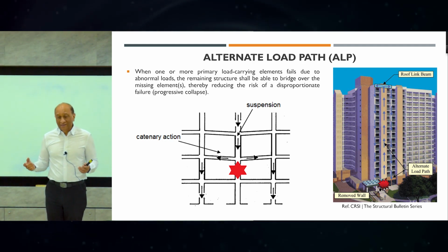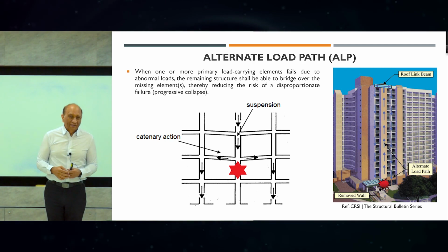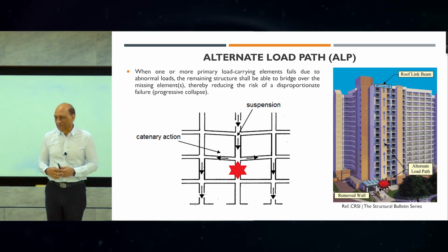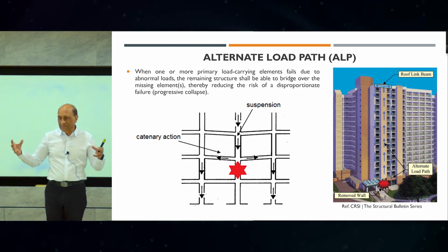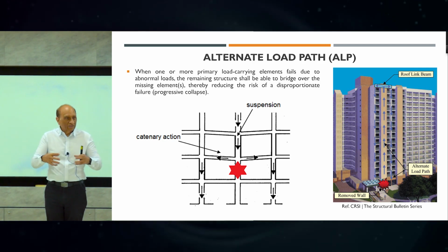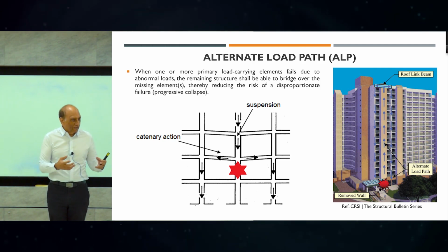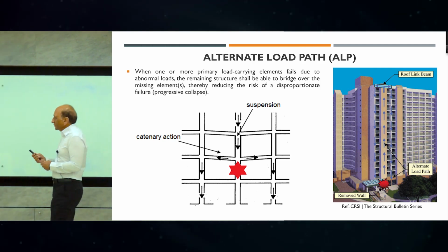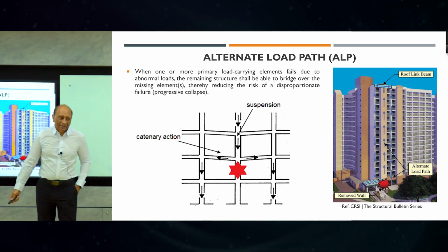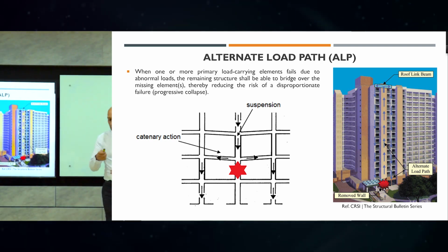And you find, surprisingly, that a lot of columns can be taken out and the building won't fall, because there is a redistribution mechanism in the building. Because of the stiffness, it carries the load back to distribute to other places. It will have a deflection, but not failure. Okay, so that is something that, in fact, there was a building in India, similar to this one.